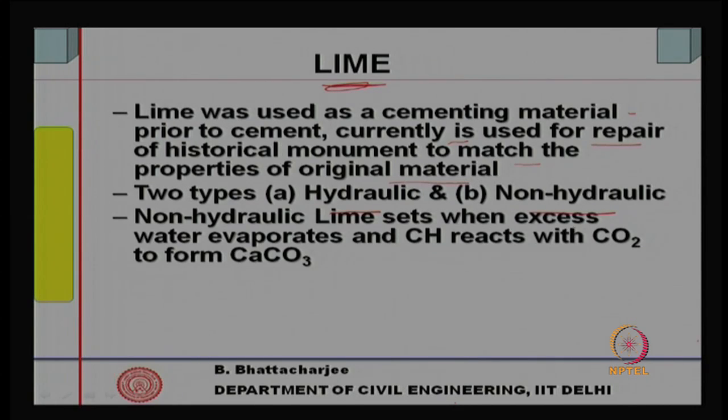Non-hydraulic lime sets when excess water evaporates and calcium hydroxide reacts with carbon dioxide from the atmosphere to form calcium carbonate, therefore the setting occurs.